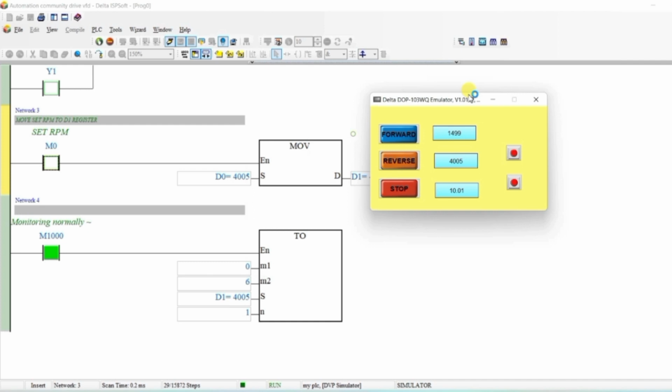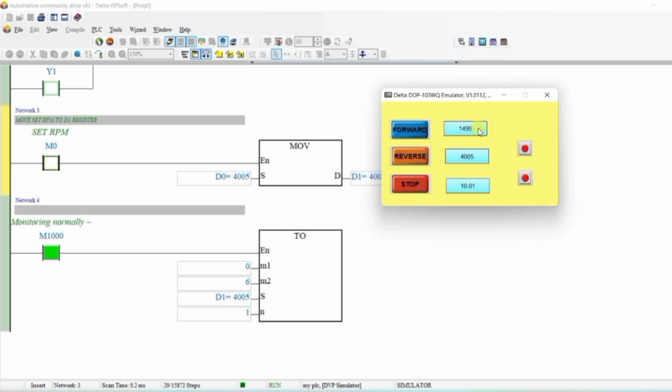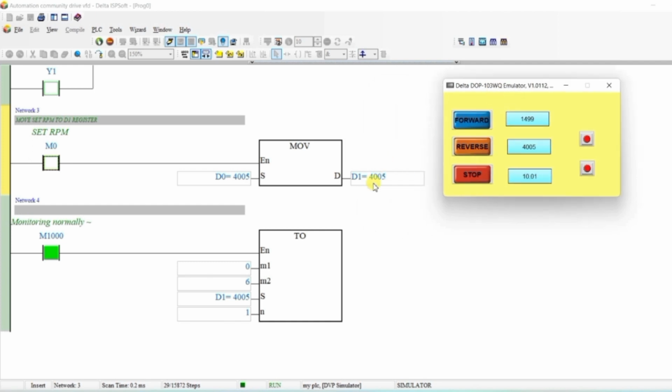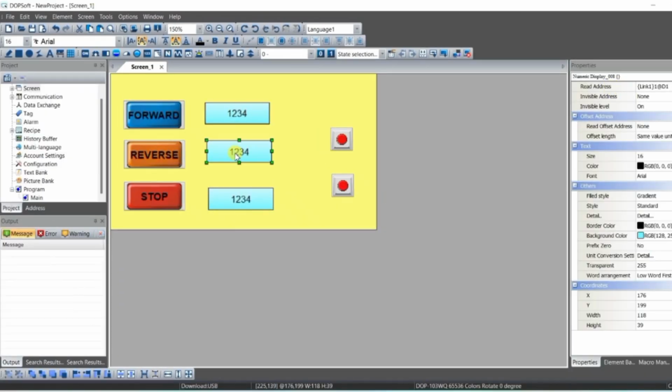So this time you can see for 1500 RPM we want 10 volts in the analog output module, and that can be possible when the data register is 4000, okay. So now our calculation for this output voltage is correct for gain settings of this output. Now let us close this. If you are feeling any doubt, just see my simulation and doubts will be clear to you.